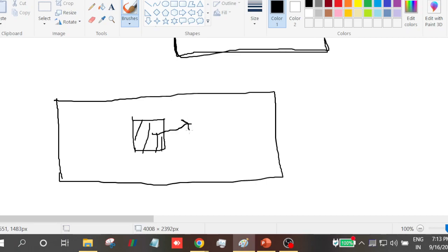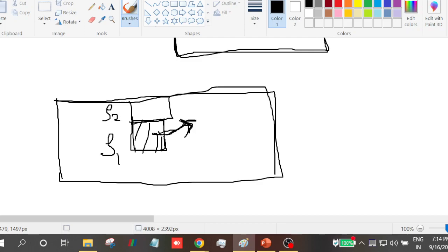Now when we trace this with respect to time, we assume that the density of this packet does not change over the time, wherever it moves. But you can have a variation in density across the domain. If this is your whole geometry, here density might be rho 1 and here the density might be rho 2, but we assume that the flow is incompressible because this packet which we consider does not change its density over the time when it flows. So that is the main difference between the incompressible fluid and an incompressible flow.